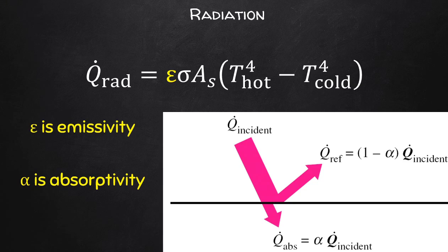And something white would be very low. Okay, so we often want to factor in emissivity as well as absorptivity when we consider radiation. Keep this in mind and consider how you would use these two principles. If I give you information on absorptivity, would you be able to determine emissivity? These two concepts, emissivity and absorptivity, are related to each other, where emissivity equals 1 minus absorptivity.